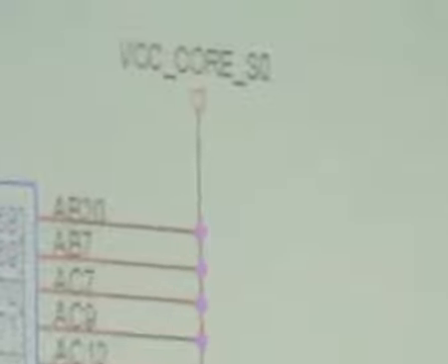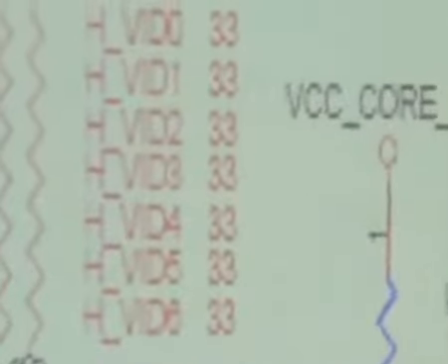We will discuss how this CPU core supply is coming. This comes from the voltage regulator. Through a number of steps, this voltage is generated. Here the important pins are the VID pins. What are VID pins? VID pins are important for self-correction, self-adjustment of the required voltage.